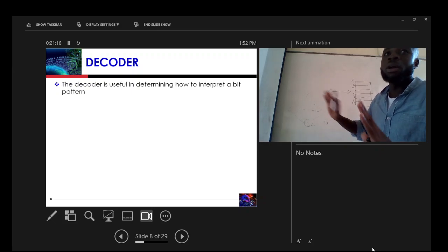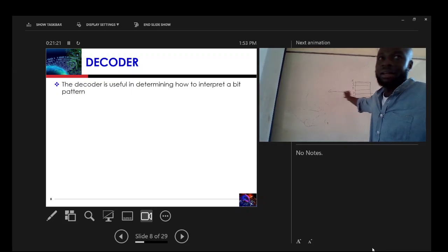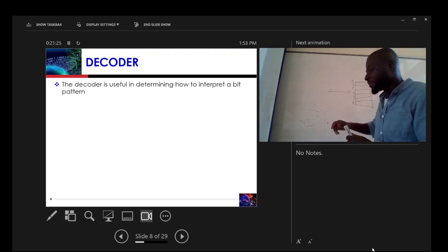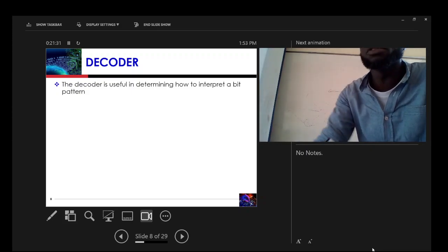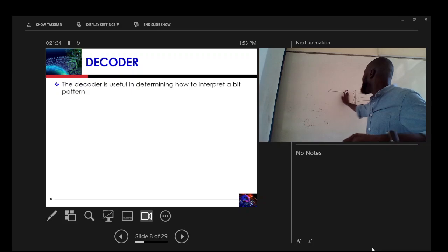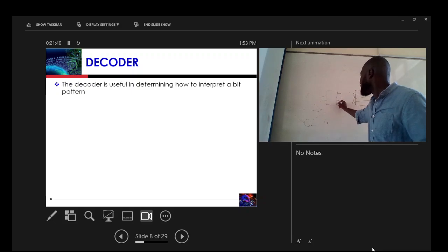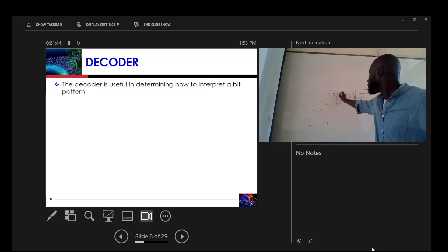You can also write to only one location at a time, because of the addresses and because there's just one line. So if you have just four locations, from 0 to 3, you have two inputs and then four outputs of a 2 by 4 decoder. Then you connect each line to this.